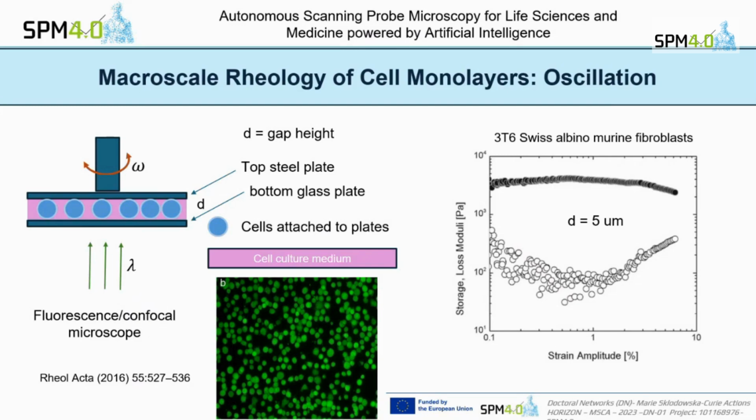And as you can see, for a gap of 5 micrometers, we obtain data where we can see linear behavior of storage modulus with increasing amplitude. So we characterize the so-called linear viscoelastic range. So in theory, all the measurements should be performed within this linear viscoelastic range.